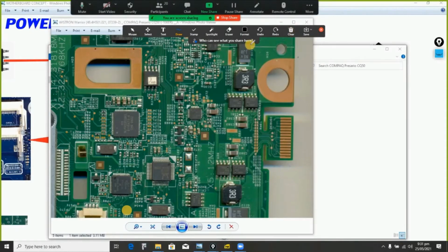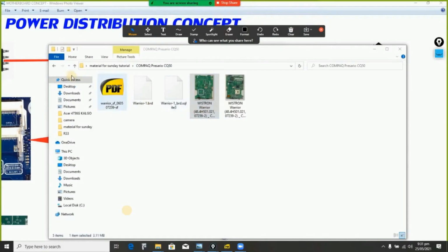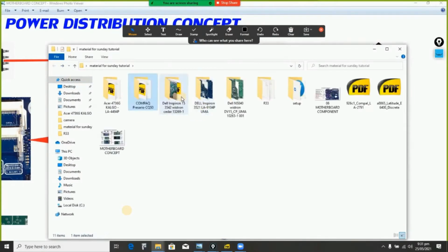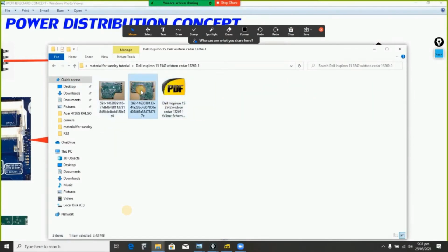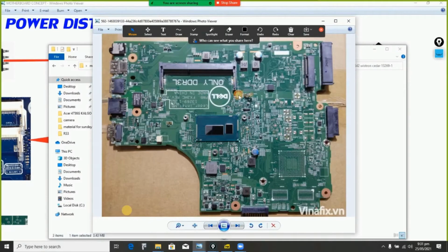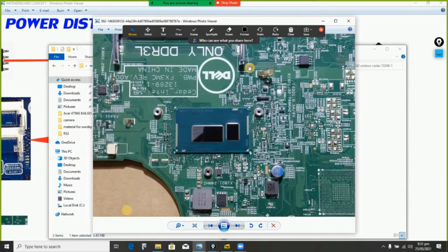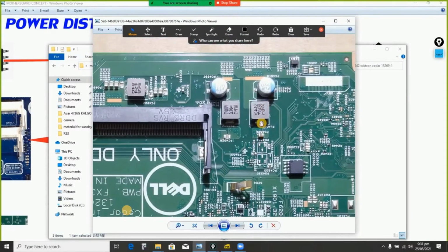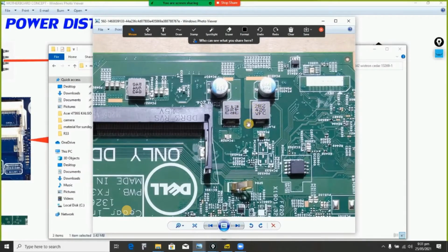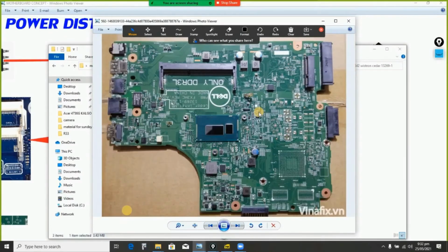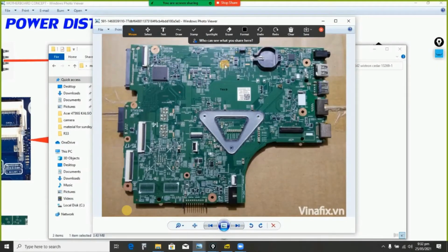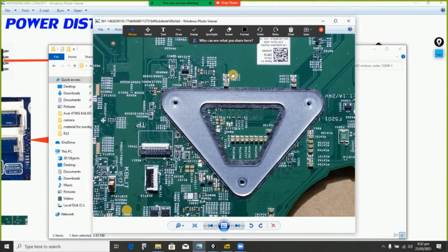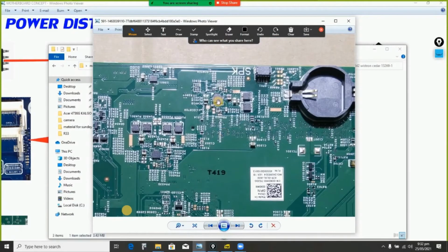So without labeling anything, I can check another one again for better understanding. This is the latest board, SOC chip. If you check here, these 2 are beside each other. So we can say these 2 are the standby IC, but no regulator here, which means if I flip the board to the other side, the regulator will be there. So this is the regulator here.